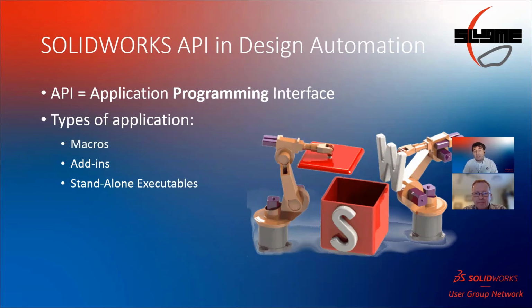There are multiple types of applications which can be created based on the SolidWorks API. Probably the most common one, and most likely one you have used at least once in your work, is macros, VBA macros. There are more sophisticated options such as add-ins and standalone executables. For example, DriveWorks itself is a SolidWorks add-in, which uses an application programming interface to build those models.